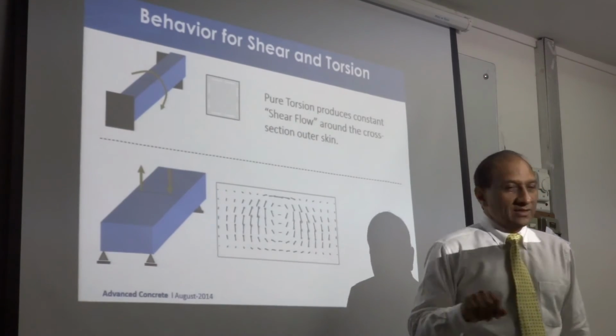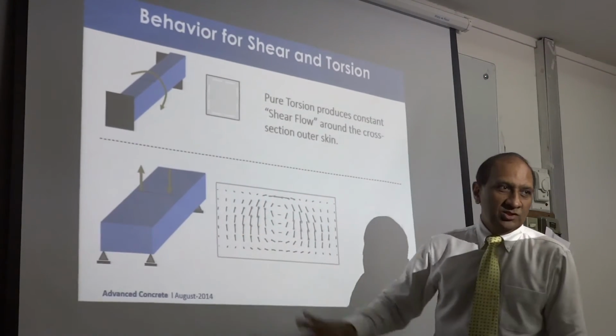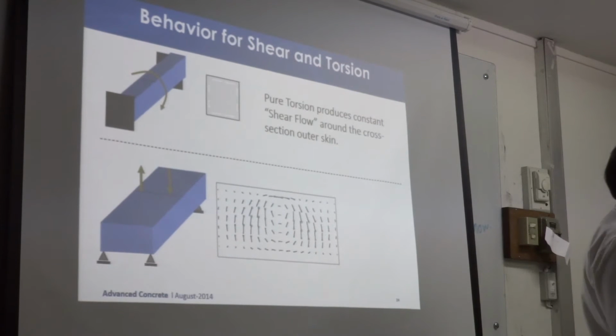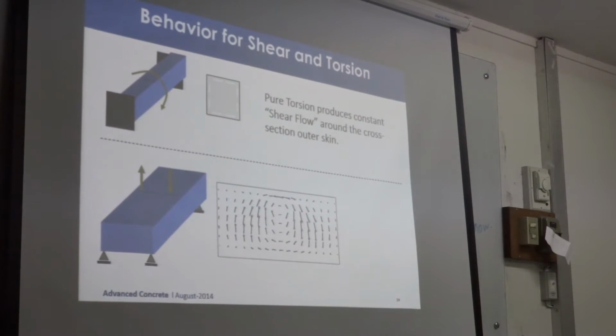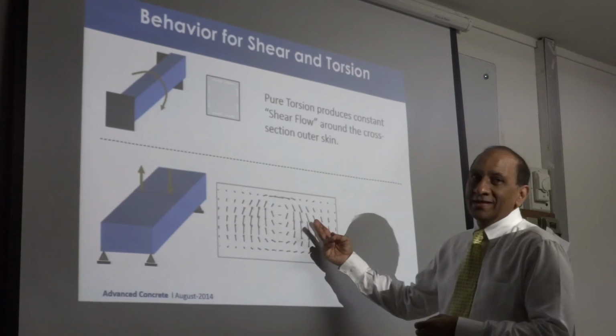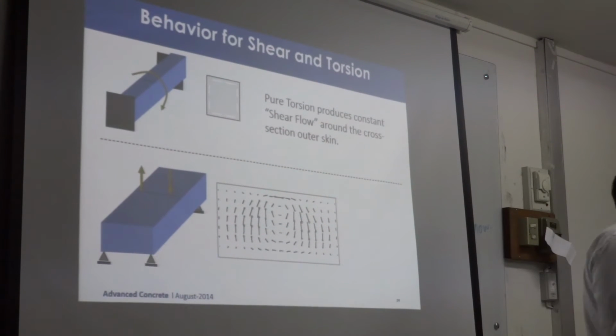Okay, shear. If the shear is vertical, you need reinforcement like this and like this. Nothing here, remember, only vertical. Right? We don't need anything else because shear is like this. So one rebar here. If the shear is horizontal, you will need reinforcement here and here, not vertical, then only horizontal. So basically you need reinforcement along the direction of the shear force. Correct? And it should be anchored properly so that reinforcement can take tension.